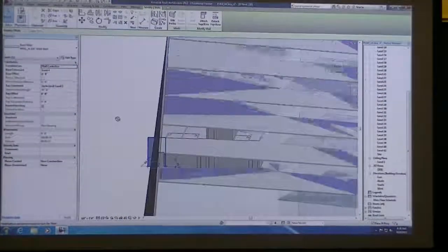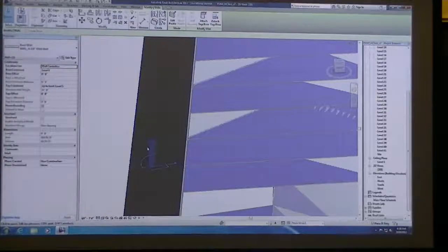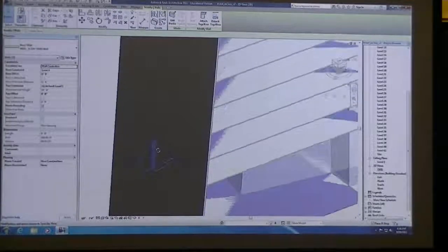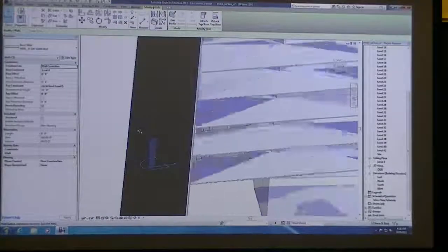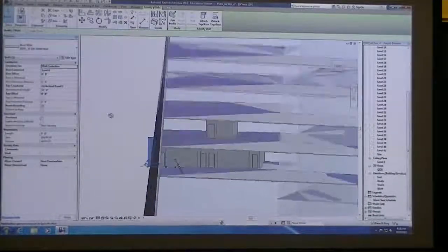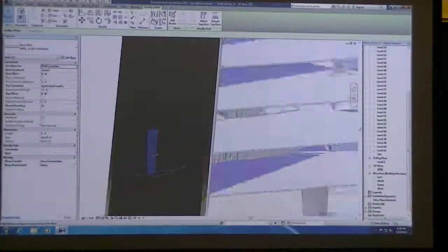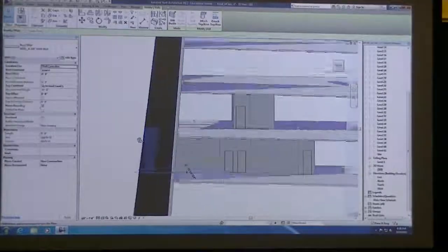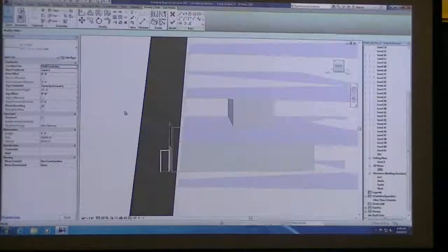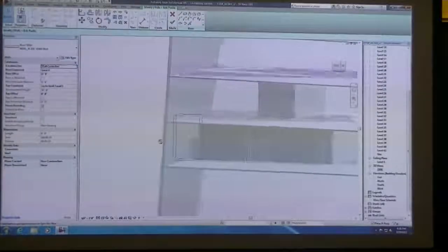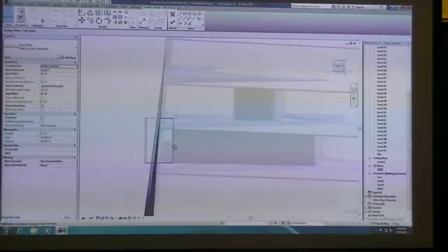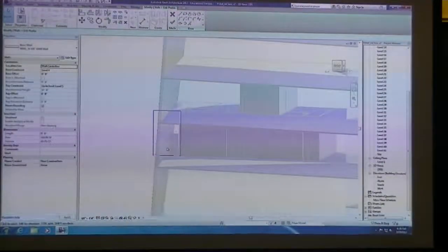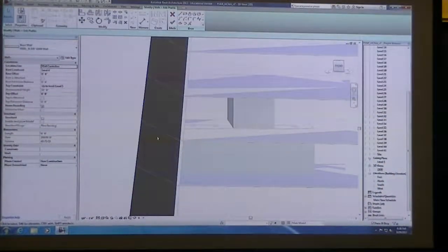But there's no way to cut this geometry, and I wish there was. It's on everyone's wish list because everyone's doing a lot more complex modeling in Revit nowadays. So one of the commands we can work on is editing the profile. I started showing you that in last class. But in order to edit that profile and get it aligned with the wall, we need to figure out where the intersection is.